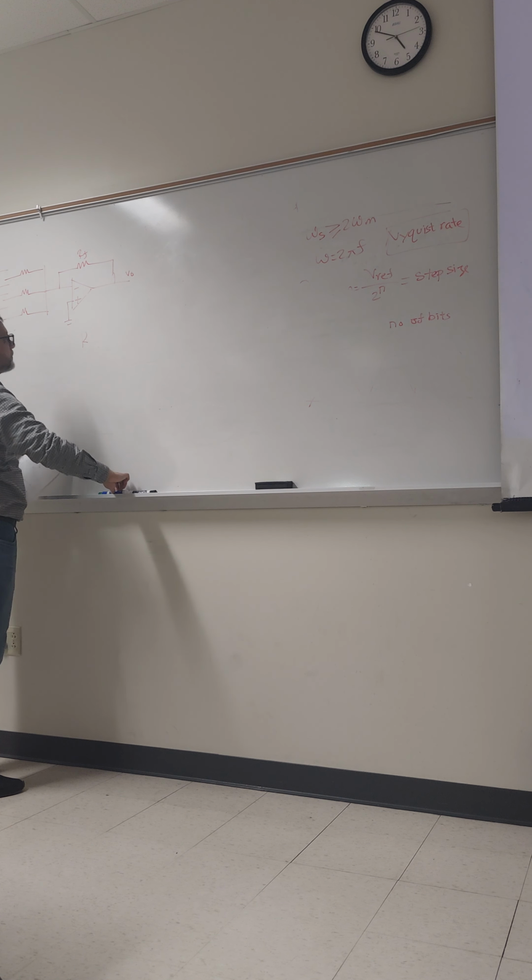So you can put that full scale output voltage equation also. You can find it. What will be the minimum input voltage? Sorry, minimum output voltage. 0. Anything else? Minimum output voltage will be the 1 LSB. 0 means you are not doing anything, right? So if you have the minimum 000001, the minimum 1 LSB, that minimum step size will give you the minimum voltage.